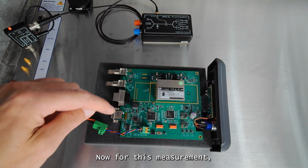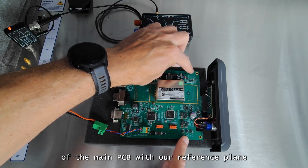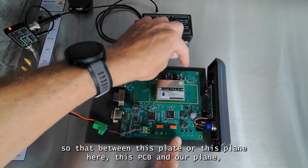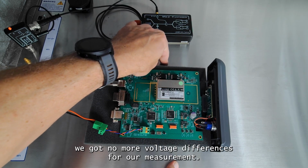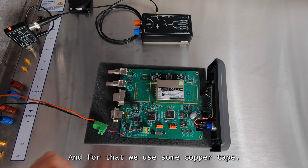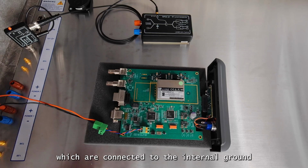Now for this measurement, we have to connect the ground of the main PCB with our reference plane, so that between this plate or this plane and our plane, we get no more voltage differences for our measurement. And for that, we use some copper tape. I have here these holes in the PCB, which are connected to the internal ground.